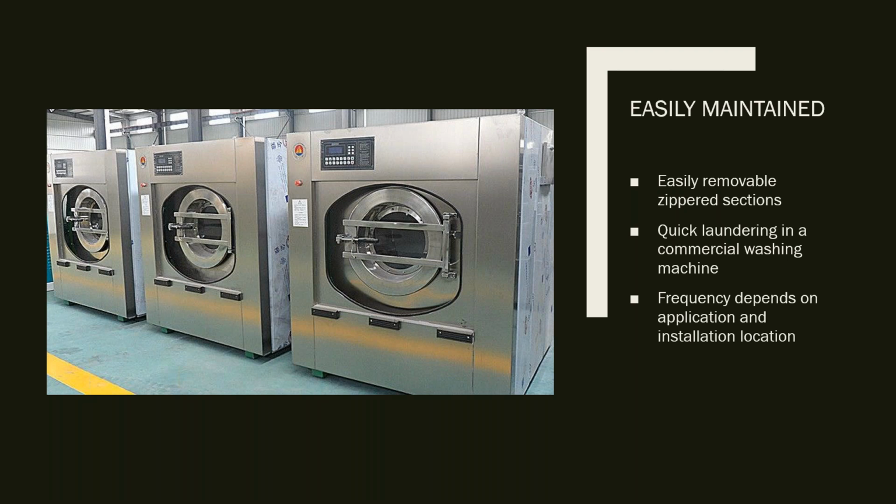But food service systems, like for your food processing, let's just say an ice cream facility making ice cream, or processing meat, or even your health facilities, they will order an extra set of ducts so that there's no downtime when they take one set down to wash them. And especially for times like this where people are concerned about disinfecting their fabric ducts, this is possible.